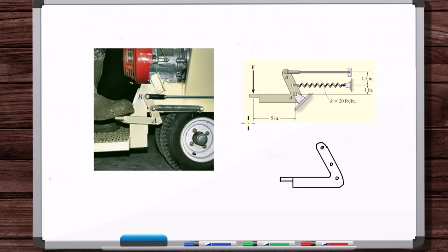And you can also think about that on a component basis. Maybe you know the X component of a force, but not the Y component. You could break it down that way too. Or if you're working in 3D, you know one direction angle or two direction angles of the force, but you don't know the third, right? You know alpha and beta, but not gamma, for example.